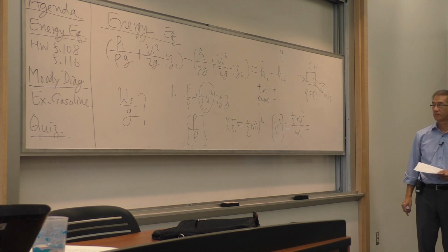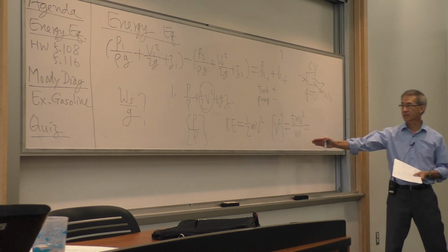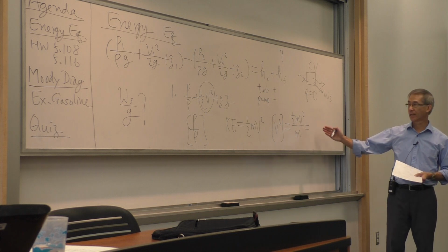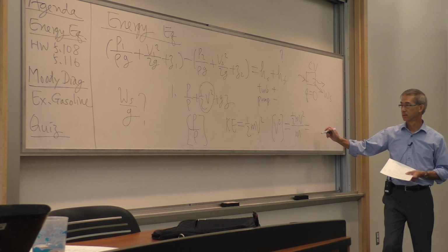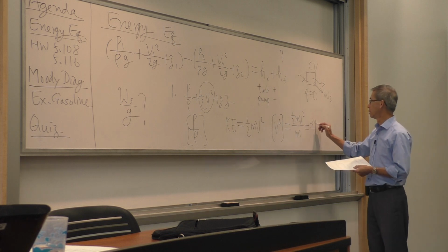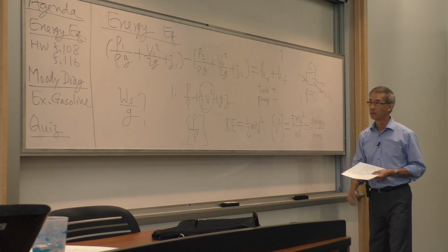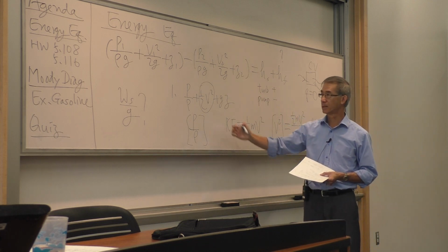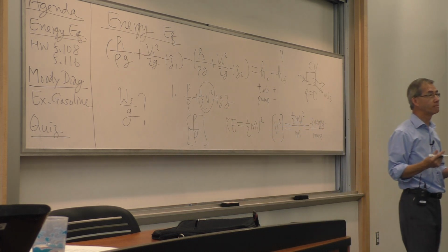This is all looking at units. So half m v squared, which is energy divided by mass, will give me a unit of v squared, which then the answer for this is what per unit mass? Energy. You've seen it before. I just hope you will remember that. So when I have the equation of energy of Bernoulli expressed in this form, it represents energy per unit mass.